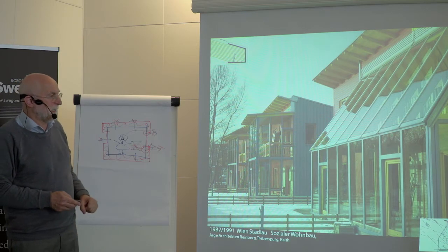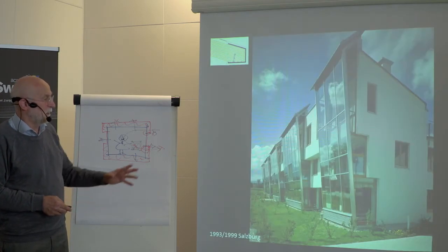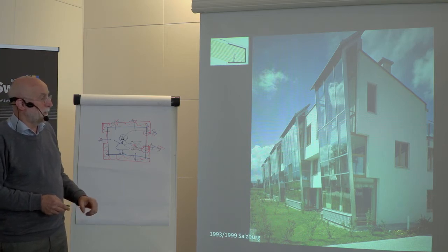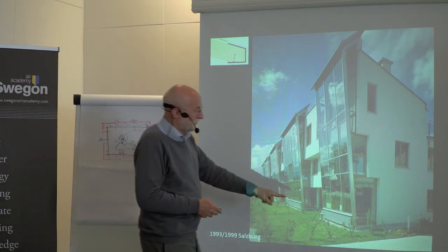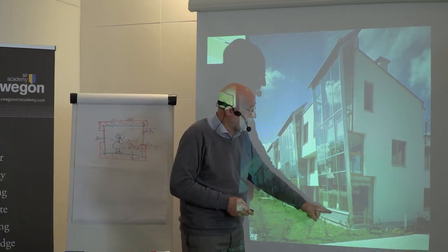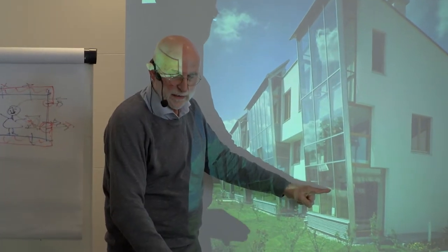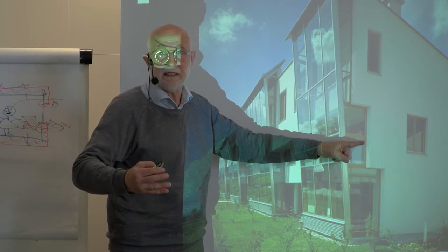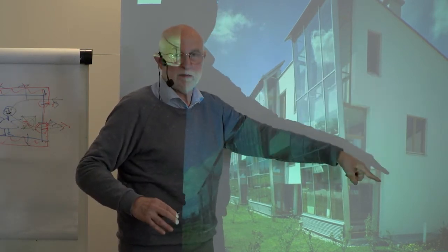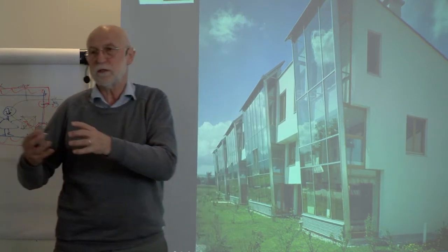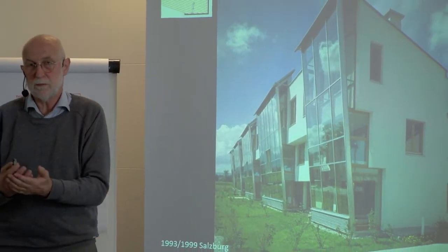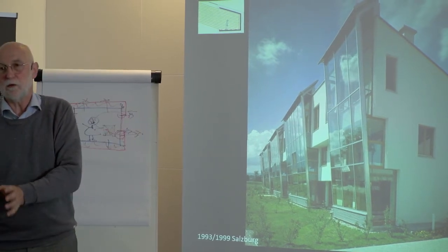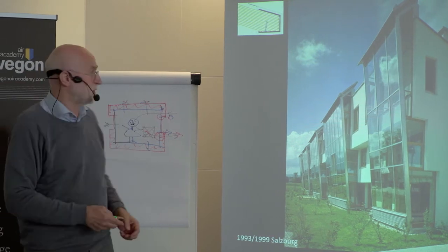Winter gardens with indirect solar gains. Winter gardens in Salzburg in a bigger project. And air ventilation here functions in that way that air is sucked into the winter garden. The temperature goes up on a low level and goes inside the house preheated. And the heat recovering of the ventilation system gives the heat to the common rooms. It's a social concept. The waste, the rest energy of ventilation is giving to communal rooms which the people have together.